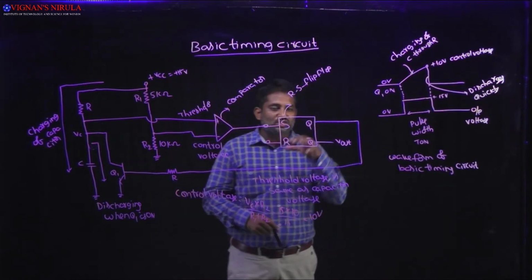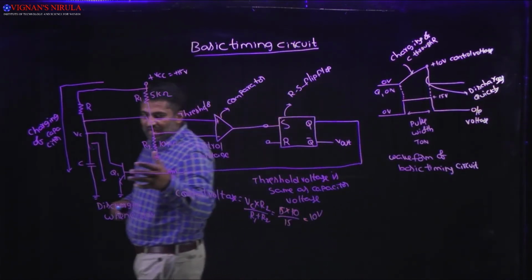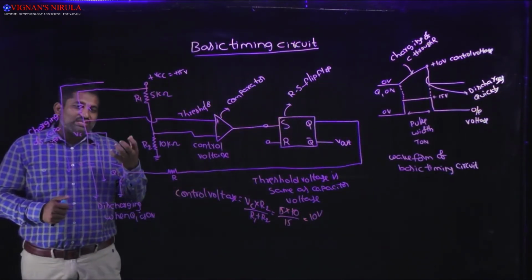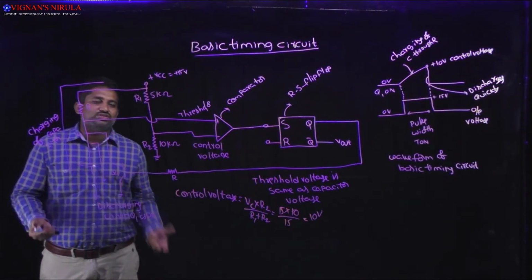What happens if S is equal to 1? Immediately Q will be equal to 1, which drives the Q1 into saturation. Then immediately the capacitor discharges.